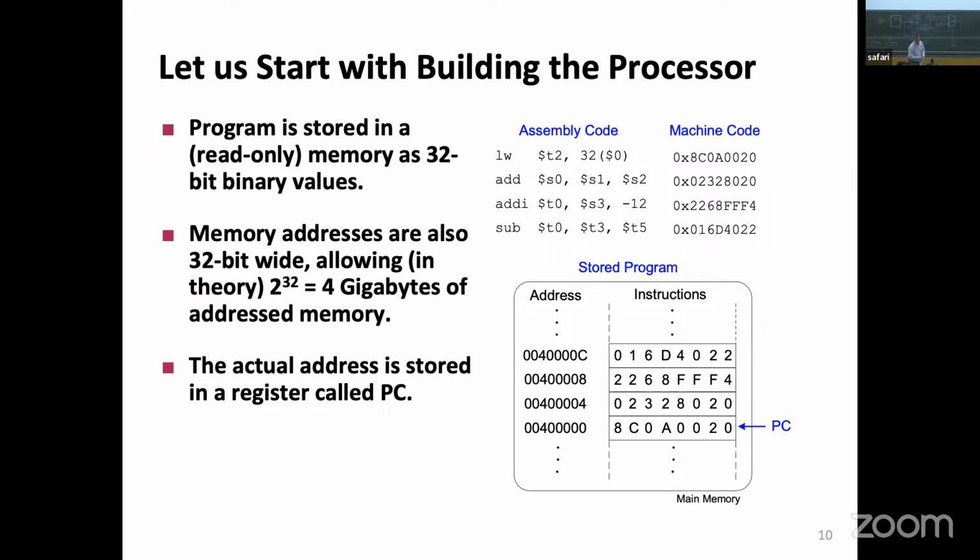And I have yet another control signal going down to my control thing. And this one we are calling ALU source. ALU source for an R-type instruction was 0, and for a load word type of thing it is 1. I will choose this input for the ALU. I will get the value from the instruction, the first 16 bits, and I will blow it up to 32 bits.